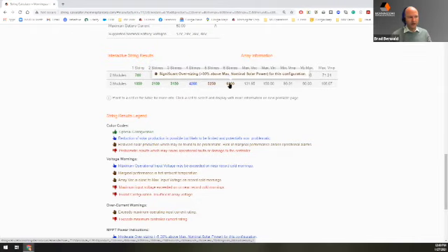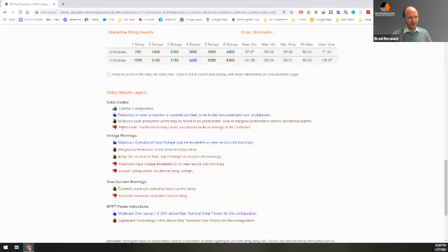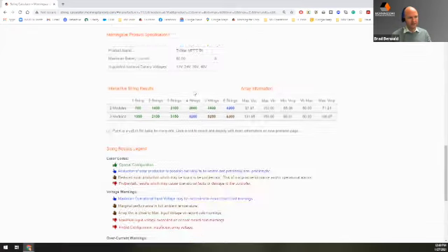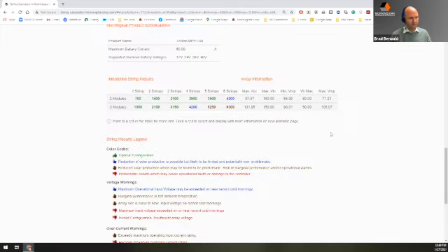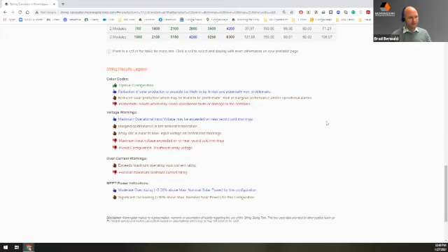And if I go up too high, you're going to see significant oversizing, greater than 30% of nominal power, indicating that you're putting way too much PV on. It's not going to be of an economic benefit because it's just oversized. In some cases, if you actually exceed the open circuit voltage, then you would actually get damage, and you'll be notified of that with a red indication. Luckily, we don't have any of this in this application here. Okay, so that is the string sizer.